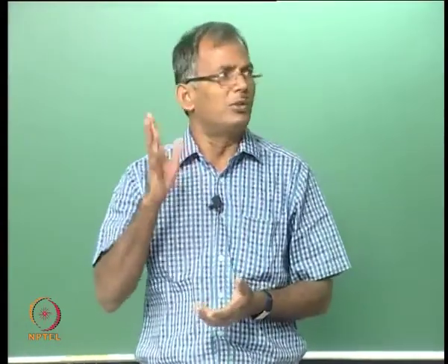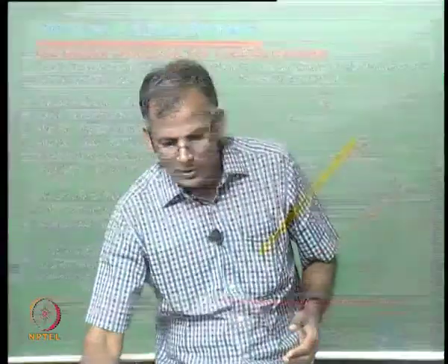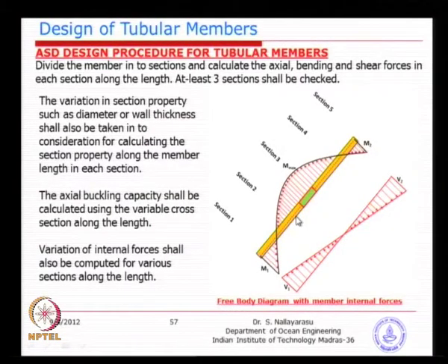When you design a structural element, it is not just one simple calculation. You should look at the whole member and divide it into several subsegments, looking at the composition of forces on each section. You look at a quite simple diagram of bending moment distribution along the length and the shear forces, and you might also have axial force variation, though axial force is normally uniform in most of the sections. What you might actually have varying is the section properties.